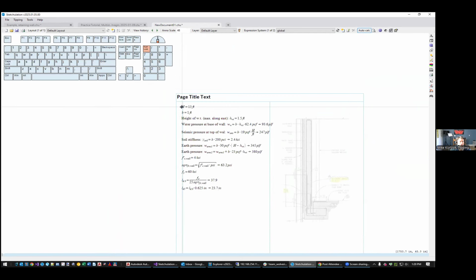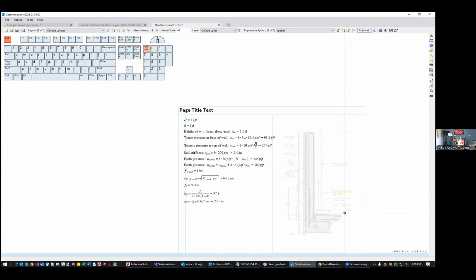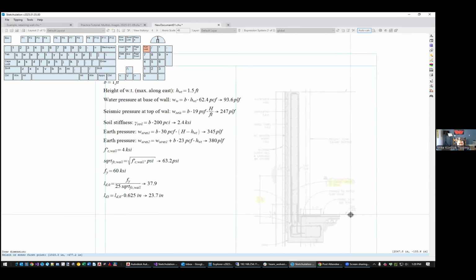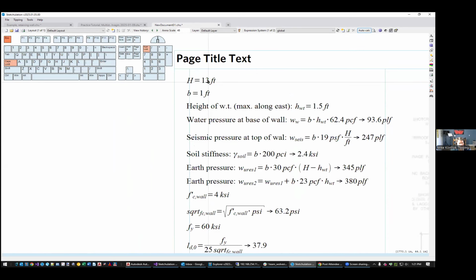Okay, let's just go through this. So I'm using just a few variables, H. If we wanted to, we could draw H on here for the plan reviewer. We know that's 13 feet. So I'm going straight up with the angular constraint, and that's 13 feet. But I'm going to replace that and just call this H like that, so it's clear what I'm using. And then I've defined H over here in my expressions.